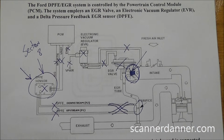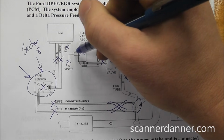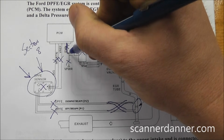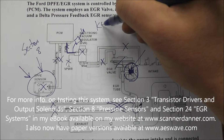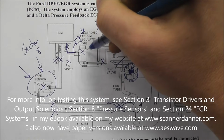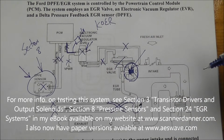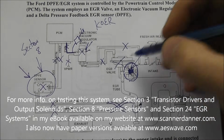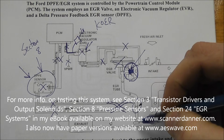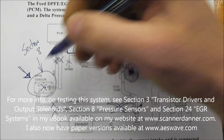So here's what I'm going to do with you guys for this video. We're going to focus on the DPFE for sure. But what we're going to do is we're going to be the computer, and this is a ground side switched circuit right here to the EVR. We're going to take a test light to ground with key on engine run at idle, and we're going to energize the solenoid. We want to hear the engine get real rough. If it does, that means the valve opened and the passages are clean, and then when we do that, we want to focus on our DPFE signal at the same time over here. We're going to watch that signal.